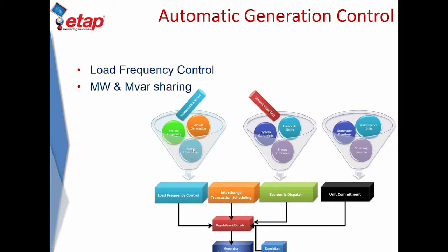So the frequency control allows us to control the network when we are grid connected, and it automatically detects when the system has been islanded from the network, and then starts regulating the internal frequency of the isolated system.